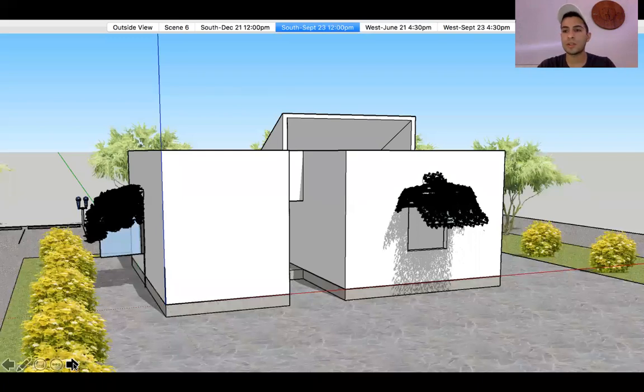So then this is kind of what the two designs look like on the final building. This is the entire structure itself. And so you can see here again on the right side, plenty of shade on the window, but also on the wall. So this is something that, of course, bigger planter box, bigger vine. This vine can grow upward onto the walls, onto maybe the roof. And this, of course, will provide more of a buffer zone between your wall envelope and your vine. And so this little air buffer zone will essentially allow the building to remain much cooler. So in the desert environment, that could be very important.